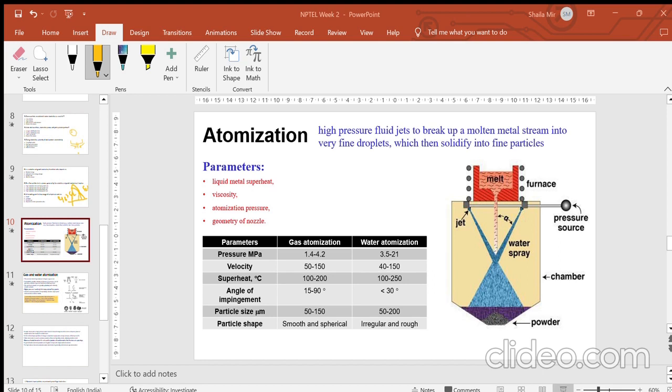Then, which of the following depicts the stages of molten metal disintegration? Wave, ligament, powder. Wave, ligament, fine droplets break down to smaller particles and then to powders. Wave, ligament, fine droplets, and then break down to smaller particles, collision and coalescence of the particles. Or D, wave, ligament, fine droplets, and collision and coalescence of particles. I think D here also. Okay, the answer is C.